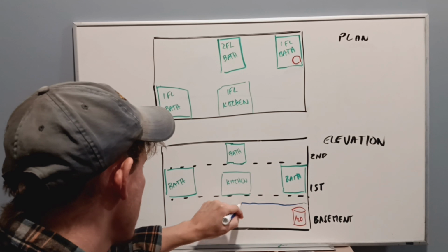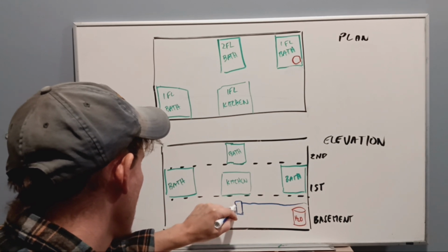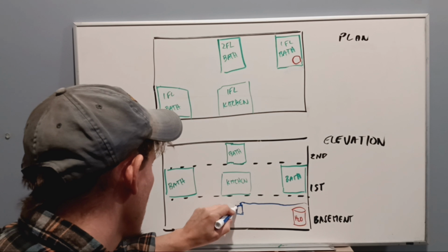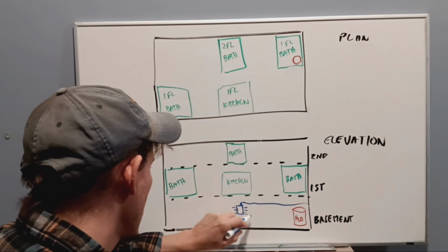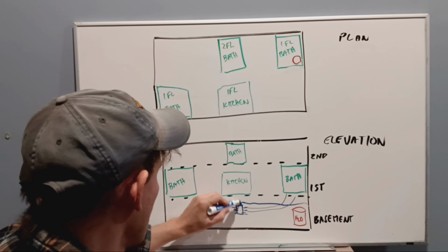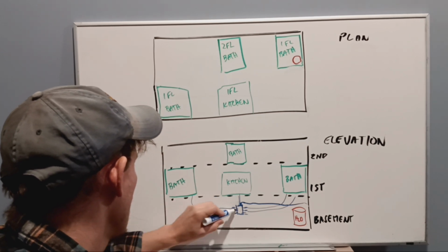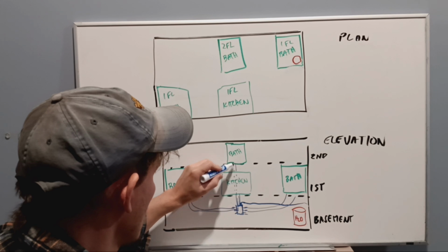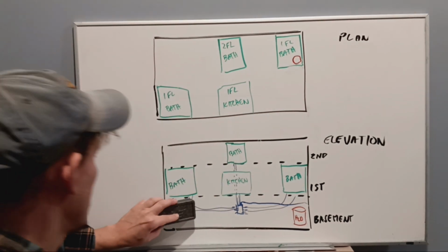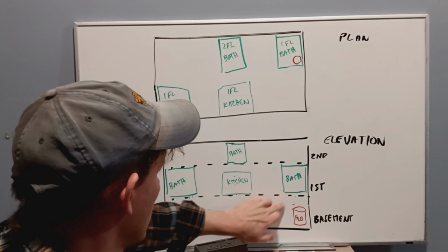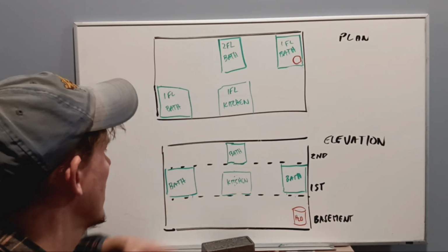First, let's look at the cold water system. Cold water comes into the house and is routed to a central manifold by a 1-inch pipe where it branches off to its various locations for use. This is a typical design that is often used for both hot and cold water feeds. The issue with this design for hot water is that over time, the water in the system cools down and you have to drain the cold water in the lines before you get the warmer water back to your faucets.